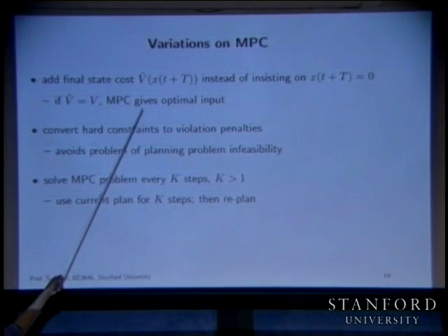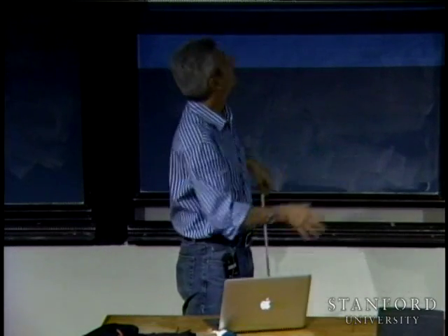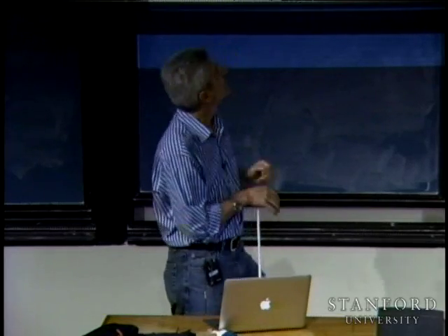So you might imagine, for example, the endpoint condition, x of capital T plus capital T, is 0. That is effectively a v hat. It's the following v hat: it's 0 when x is 0, and it's plus infinity otherwise. Not exactly what you'd call a superb estimate of the cost to go. But anyway, you can put in an approximation of a cost to go here. It'll work really well. For example, if a problem is linear quadratic and 0 is in the interior, you can actually solve the Riccati equation and put x transpose Px as this thing, and you'll get amazingly good controls at that point. So that's one thing. And it also deals with the non-feasibility issue quite gracefully. In other words, when someone says, can I see your plan, it's not going to be NaN as inputs, right?